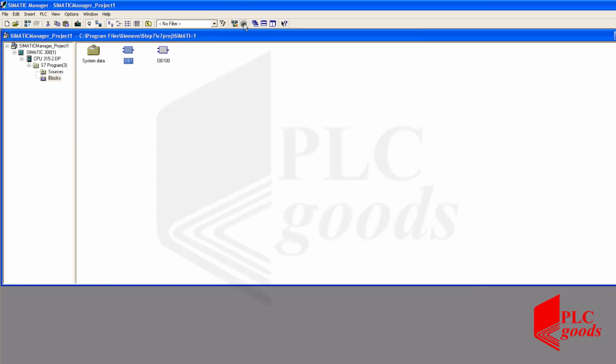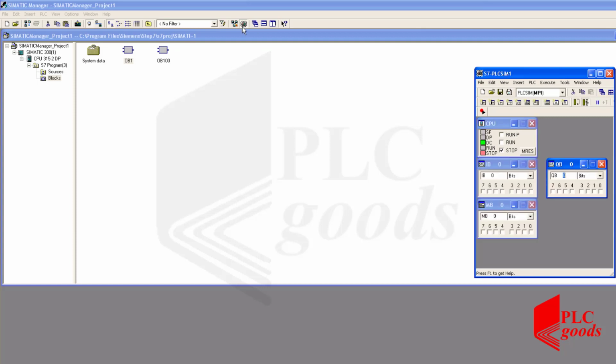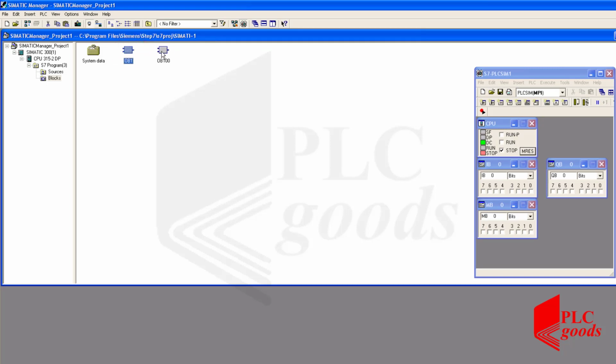First, I need to run the PLCSIM simulator, where I can click on MRES to reset the virtual PLC. Also, let me select this item, always on top. Now I can select OB1, OB100, and also the system data, and then click here to download them one by one.